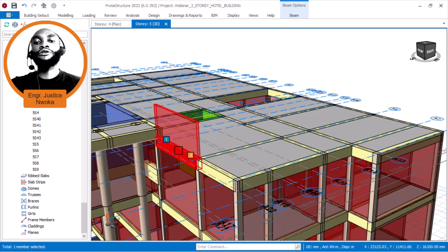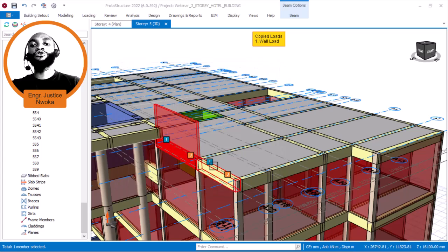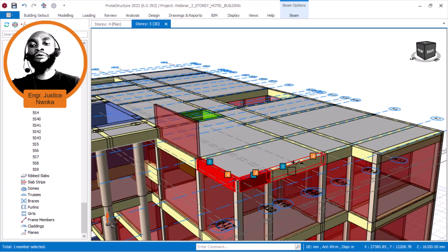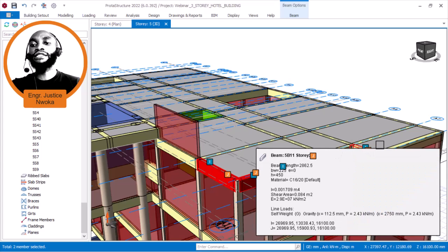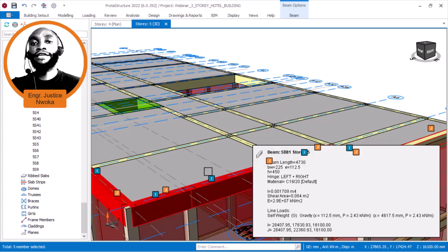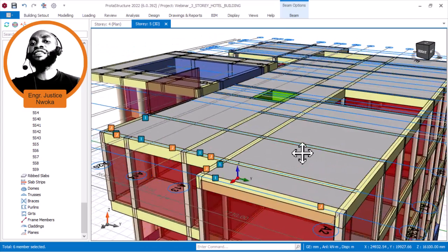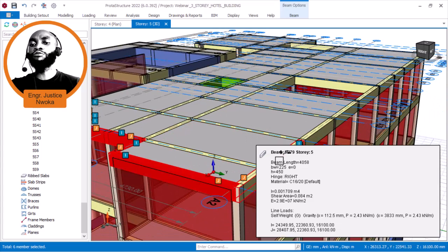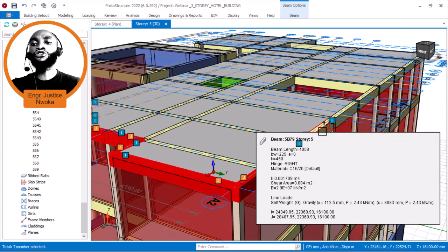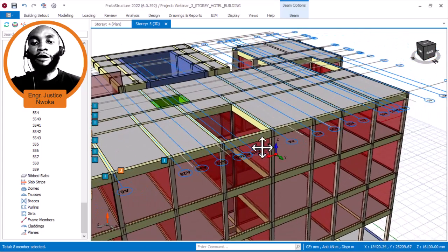So you will now be able to see that our parapet load is not showing here. So I'll quickly copy this load. I click and then copy. We'll then copy to all other perimeter walls around the roof to input our parapet. I'll hold my control key to do a multi-selection. Multi-select right now, click here also, and click this other one here, and again rotate now. So you can see how we have just done this. You can see how we spent over 30 minutes loading our basement wall and also our swimming pool. So I'll continue to paste my parapet wall.